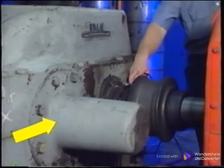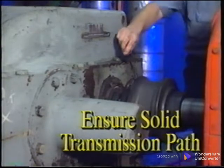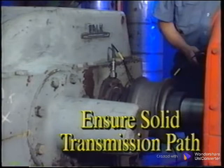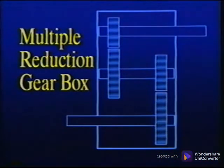As in other measurements, we need to be as close as possible to the source of the energy with a solid transmission path through a web or internal frame to the measurement location, and as close as possible to the bearings actually supporting the gears. For multiple reduction and angle gearboxes, 2 radial measurements should be made at each bearing location as well as the axial measurement. This second radial measurement should be perpendicular to the first measurement.